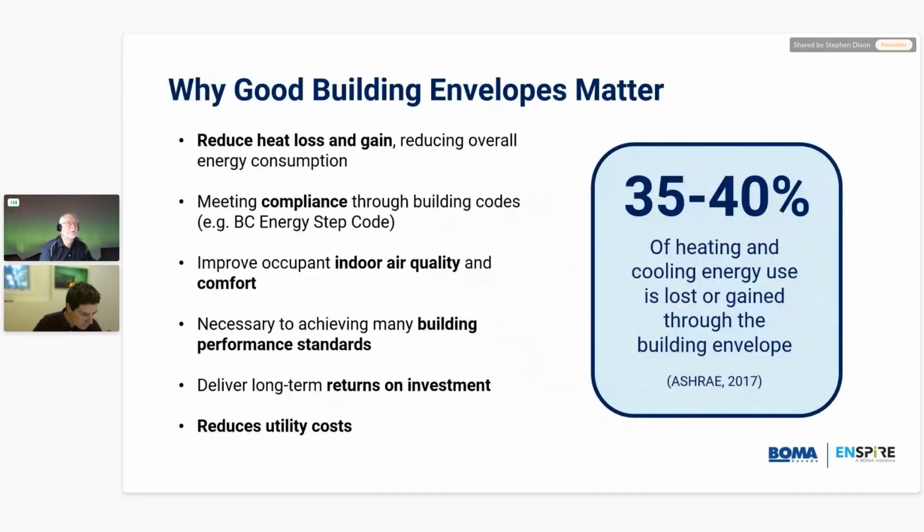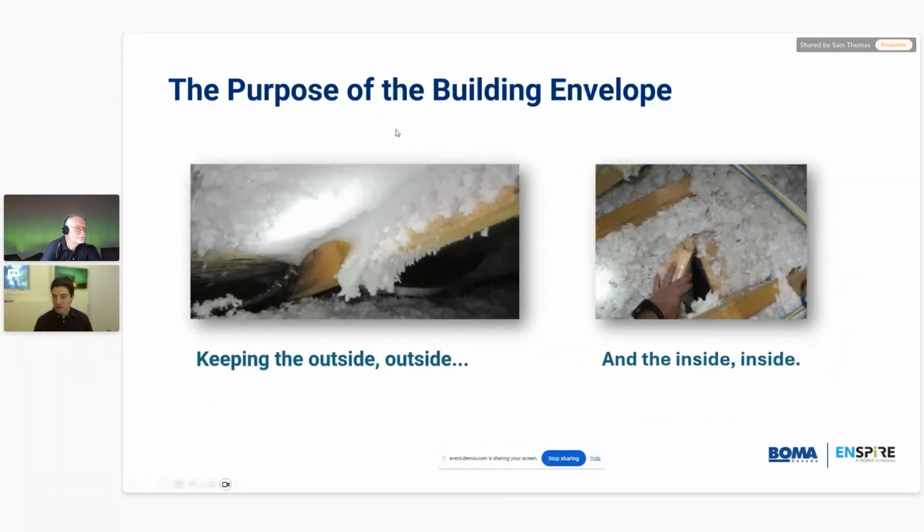Why good envelopes matter, right? I think the right-hand side, and actually I'll have an example that goes beyond that, but 35 to 40% of heating and cooling energy use is lost or gained through the building envelope. So it's a major component of any building's energy consumption, right? The purpose of the building envelope, much like clothing, is keeping the outside out and the inside in. And ultimately, this is the fundamentals of what we're trying to get at.